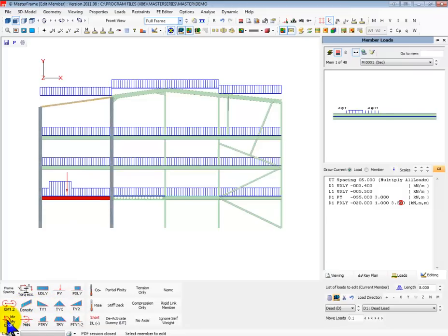We have triangular loads, we have end moments, point moments, trapezoidal loads. And now we come to the really fancy ones, because I can say that in fact I have an eccentricity horizontally of 200 millimeters, and then I have a 5 kilonewton UDL that's at that eccentricity, and then I add a second eccentricity. So only that one load, because that defines it, that applies it, and that sets it back to 0. So we can have eccentricities in the horizontal and vertical. So that's like a wall sitting on the outside leaf.